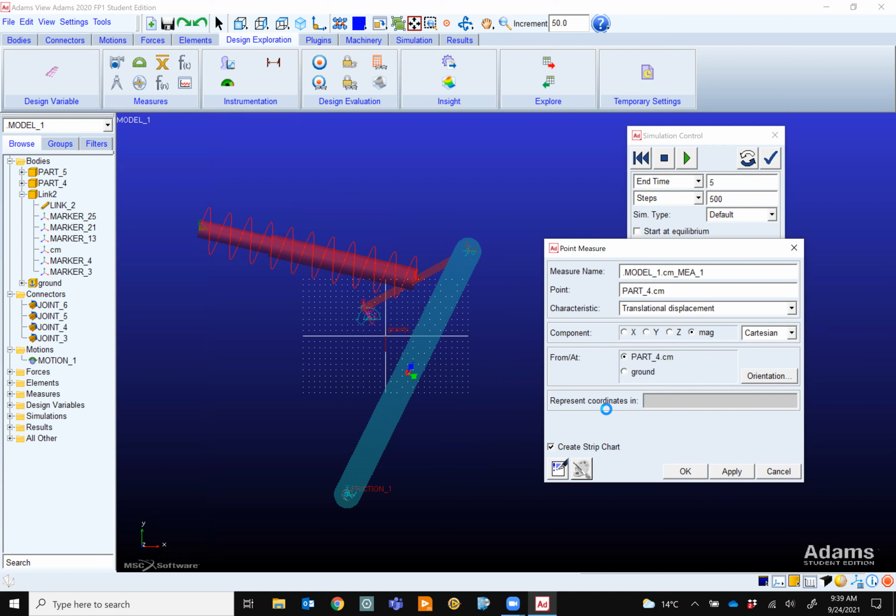It's done. We are done in 2 minutes. For you guys, should be fast. Really useful. While your program is running, you can add as many sensors as you want to measure the motion of different points, to measure the force for different joints as it's running. But you don't want to put too much data on your screen. All of these things are available later, as you saw, but this is for while we are running it.